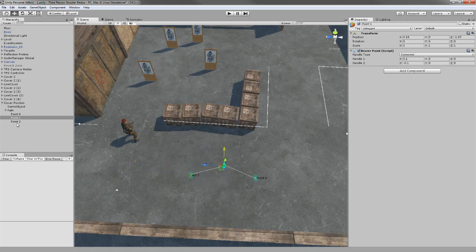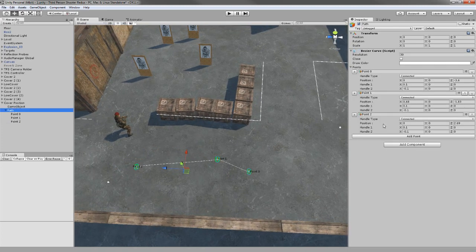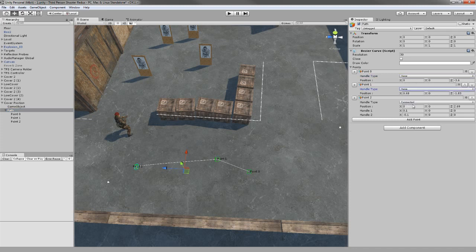Now, for the limitations we set up in the previous video, since we are not using a curve, we only want to use this as linear, or if you want to use it as a curve, so you have some smoothing, the thing I've shown before, you can choose and play with the settings. Now I'm going to choose none, none, and none, so that it keeps a linear path.